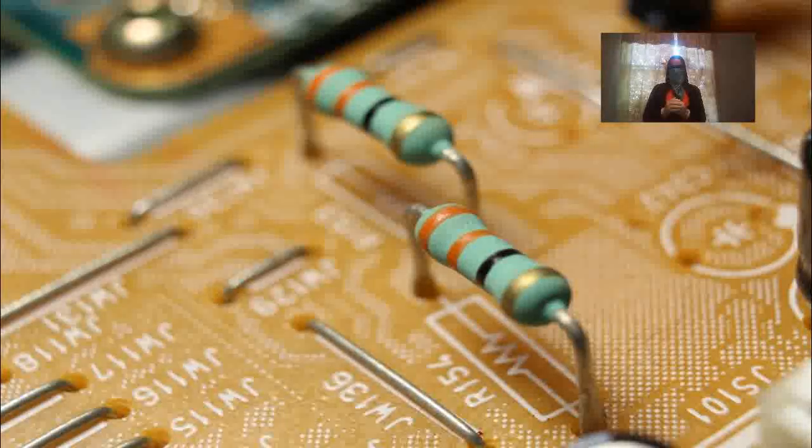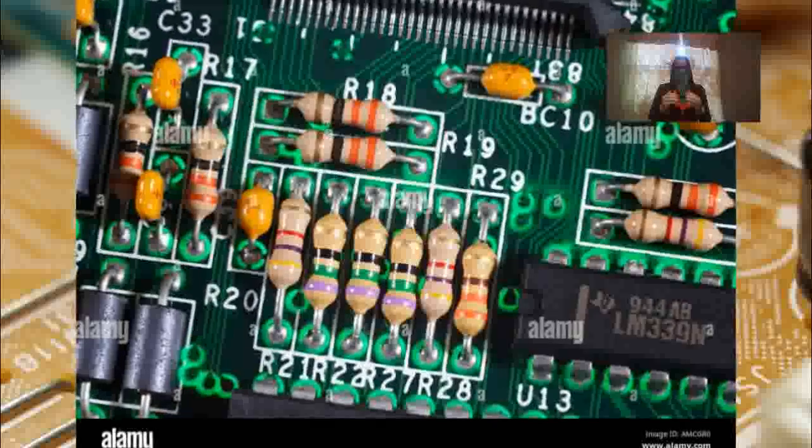However, the fourth band is silver. This indicates that the resistor has a tolerance of 10%. In this example, the tolerance is plus or minus 27 ohms. So 270 times 0.1 equals 27. Thus, the value of the resistor is somewhere between 243 ohms and 297 ohms. Work out the stated value, maximum value, and minimum value for the other two sketches in figure 3-38 on your own.